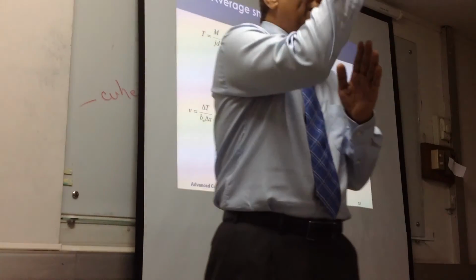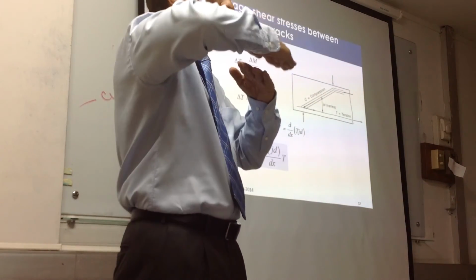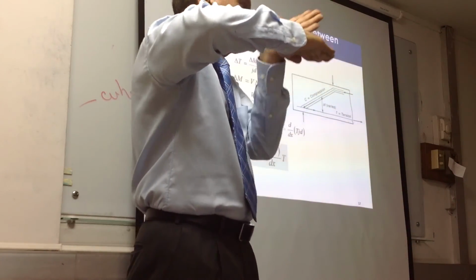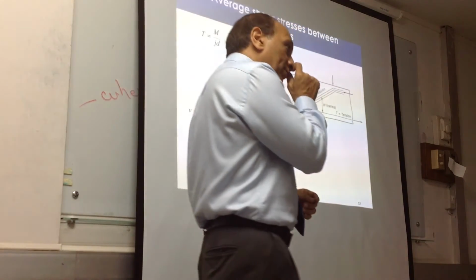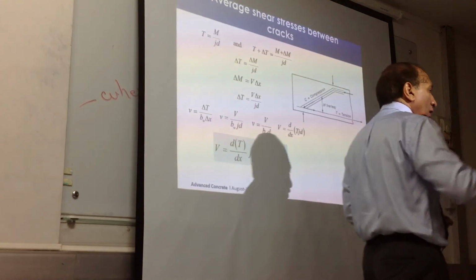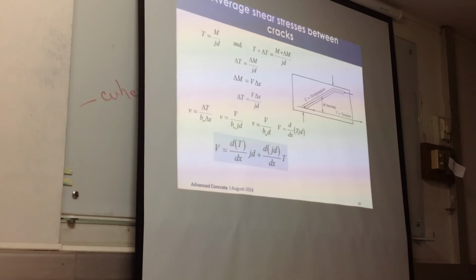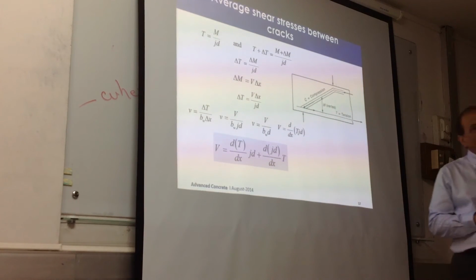So whether we provide the reinforcement vertically or horizontally, it will have a component diagonally, right? Always. So that means shear reinforcement can be horizontal or can be vertical. It has some effect, some contribution. And that is what we will study when we talk about walls, right? And beams. So we will see that the shear reinforcement actually could be provided in both directions.